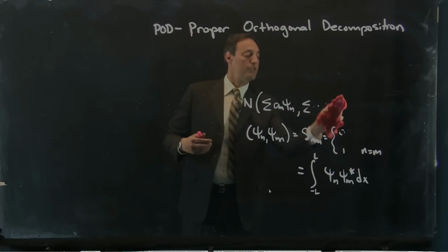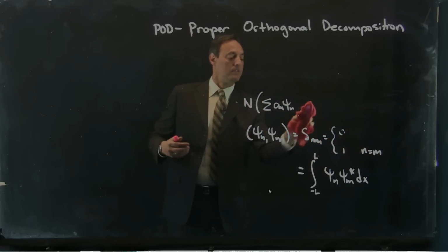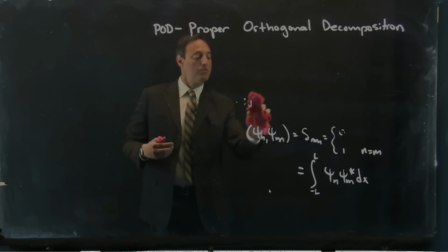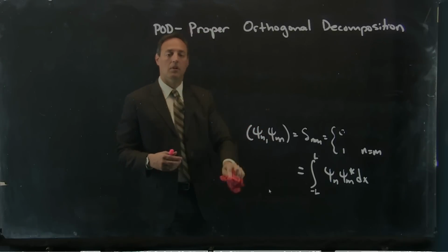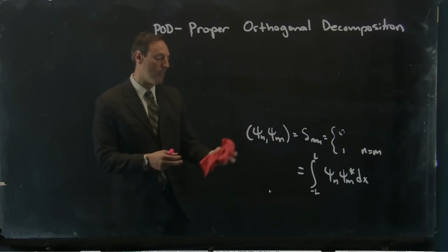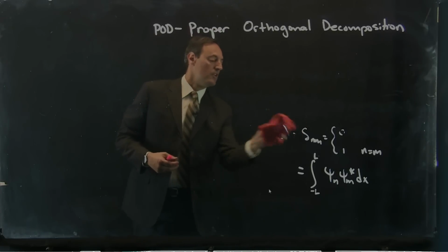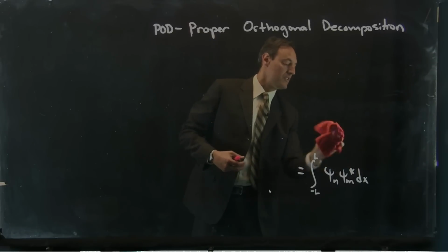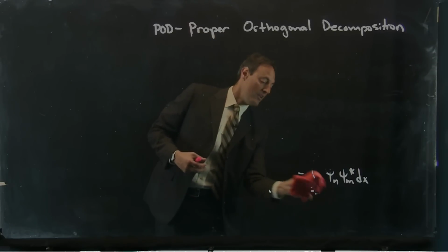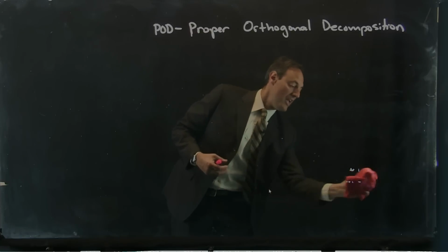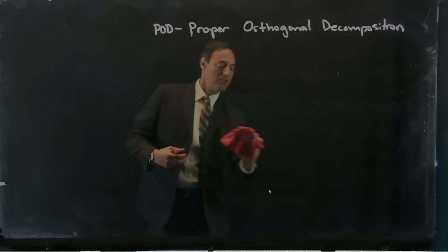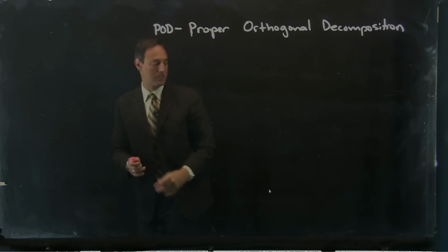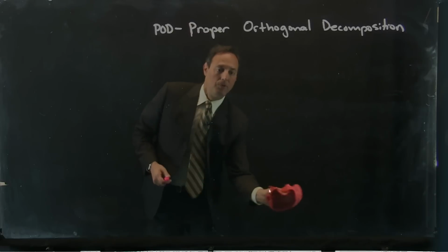Okay, so reduced order modeling is all about this basis selection criteria and reducing the space in which you have to solve for these differential equations. So you're going to start off with a very large dimensional space. You can imagine if I discretize the airflow around a wing of an airplane wing, n would be tremendously large. And if I can actually make that dimension much smaller in some way, then you would like to do that.